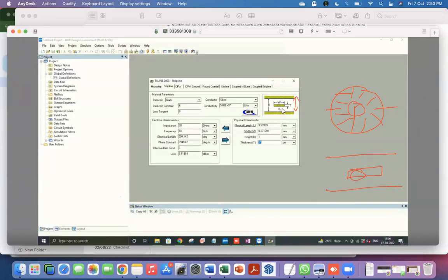For example, if you're making some kind of a transformer, say a λ/4 transformer, and that only has connections at the two ends, there's nothing happening in between. But if you're designing some high frequency circuit where you have some components, maybe a transistor, you're making an amplifier and it has to be connected, then the strip line becomes inconvenient because there's no simple way to access the center conductor.